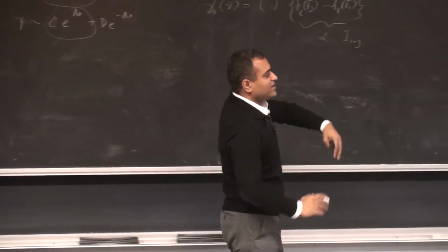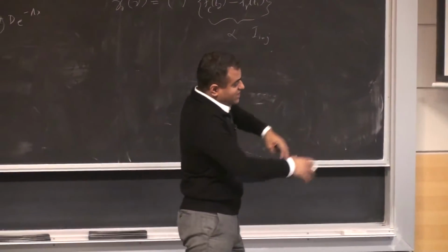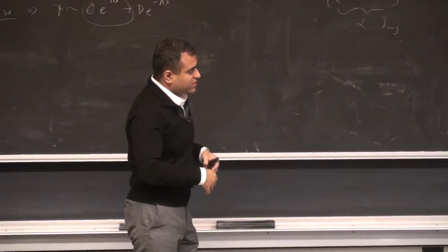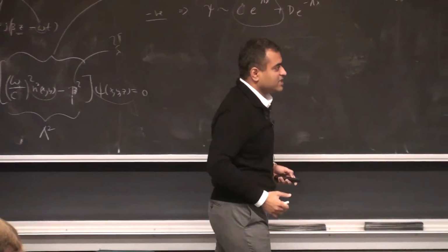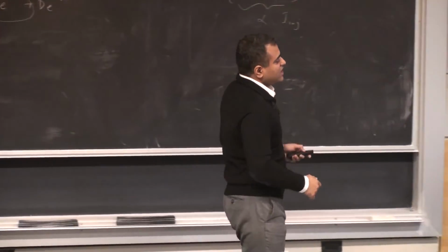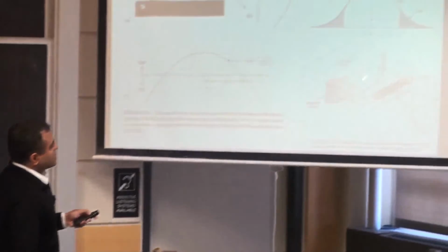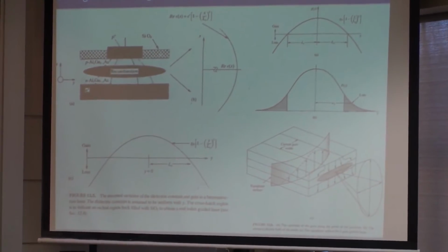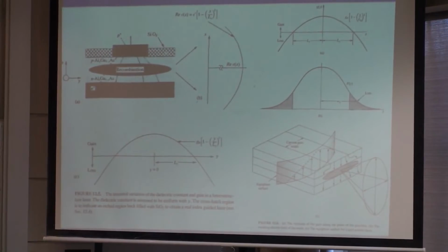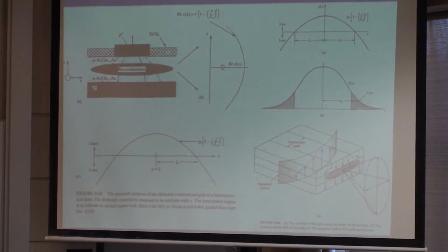This is very similar to your ABCD beam curvature. If you remember the phase curvature, it's very similar to that. In fact, that's in your book, in this chapter at least, they connect it to the ABCD parameters. You can use ABCD parameters to calculate the phase front of a semiconductor edge emitting laser as well. In laser parlance, very similar to eye surgery, this is called astigmatism. Basically, you cannot focus on one point at any time because it's out of phase, the equiphase.